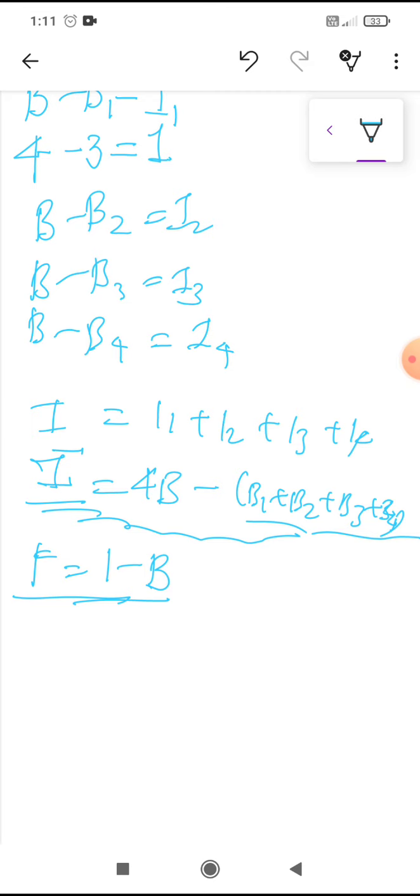So this is the Morse test. Now, what are the errors involved in this? Though the measurement of the frictional power is fairly accurate, the errors involved are these: in petrol engines, using common intake manifolds may affect the distribution of mixture and the volumetric efficiency of each cylinder, and the use of common exhaust manifolds and the cutting of the cylinders may cause pulsation in the exhaust system, which in turn will affect the performance of the engine. So these are the two disadvantages of this method.